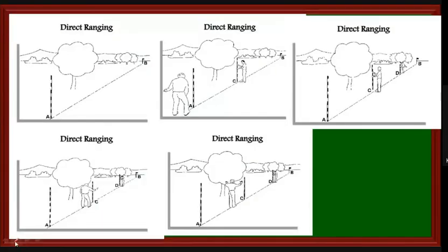This is the procedure. Here you can see I have a station A and a station B, and I have a 5 meter tape or chain. We have 20 meter, 30 meter chains, but if I take a bigger number you will get a little confused, so I am going for the smaller figure, 5 meter. I want to measure the distance between A and B, but with a 5 meter tape I can't measure the distance between A and B very accurately. So I want to establish an intermediate station C.